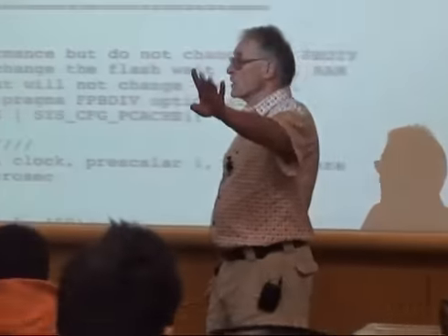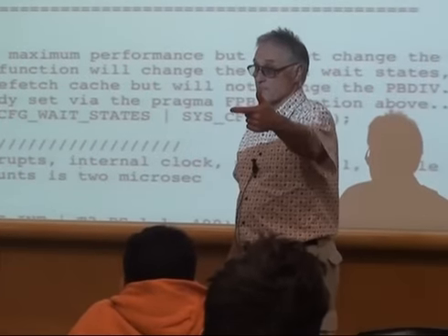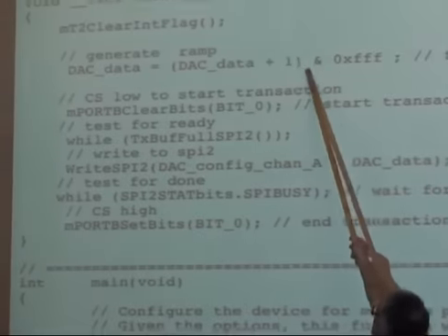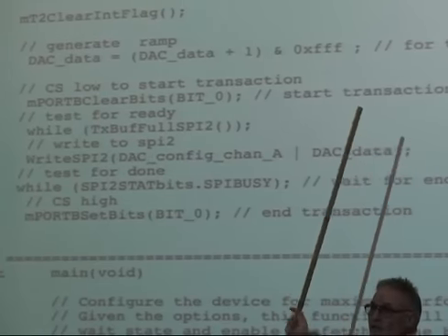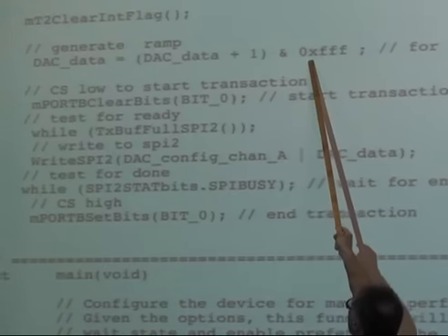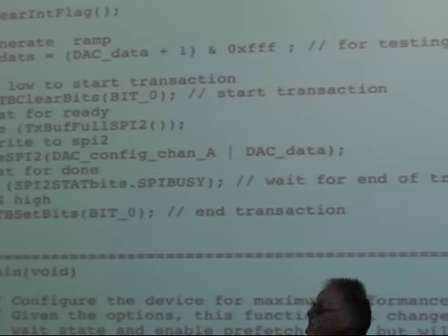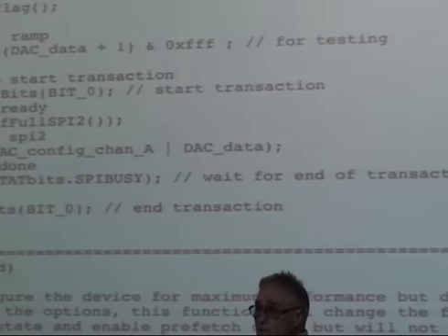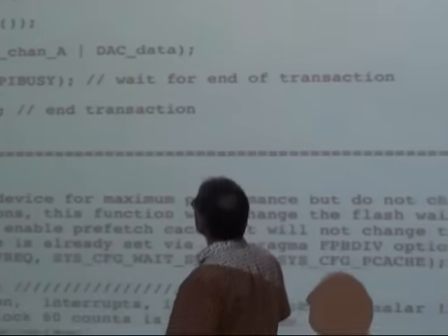Interrupt service routine: in this case, this is where you're going to put direct digital synthesis. What I put in here was just a ramp generator. So this generates a 12-bit long, 4096 step ramp at 100 kilohertz. It was easy, therefore, to verify that all the steps are being taken because it took exactly 40.96 milliseconds to execute.